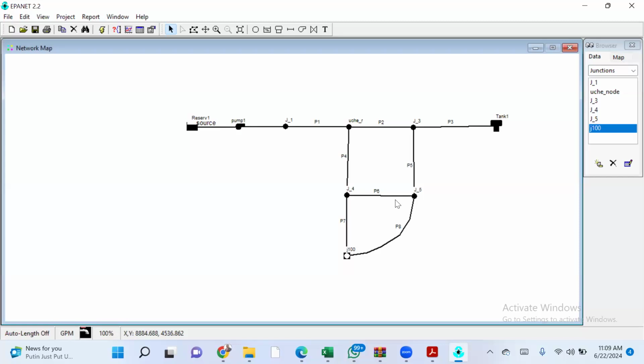Sorry, excuse me, sir. I have a question, or rather, an observation. Does it mean the same pipe? Yes, it is. I know your question. It's the same pipe. Same pipe used in supply is the same pipe used in distribution. Yes. Like I said, it's an economical design. It's not a standard. Don't see this as a standard. The only difference is going to be introducing a non-return valve to the pump so that it will not damage the pump or flow back to the reservoir. Okay.